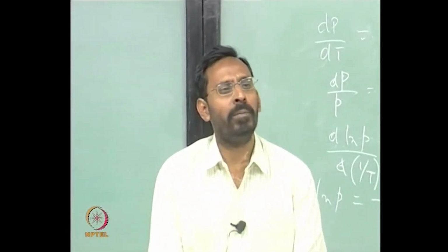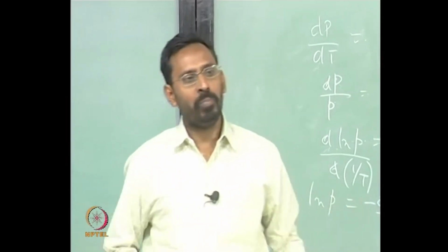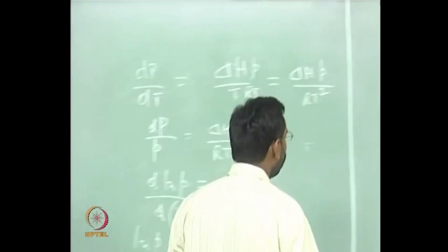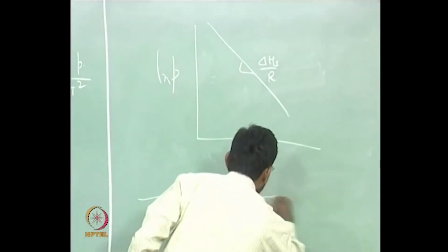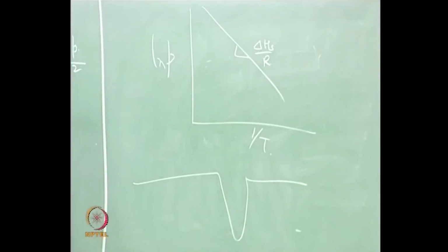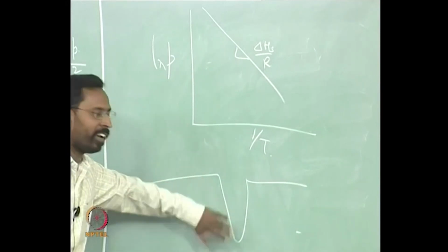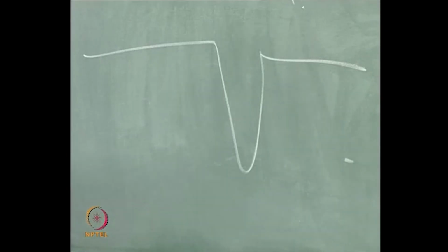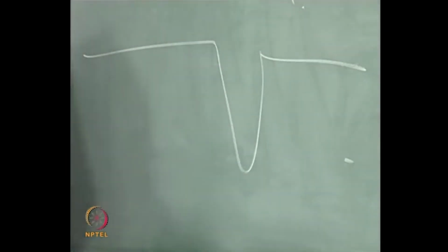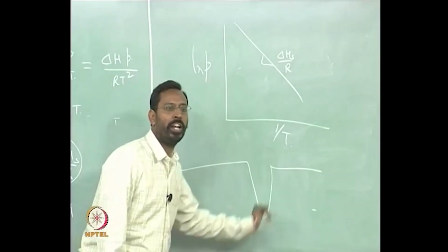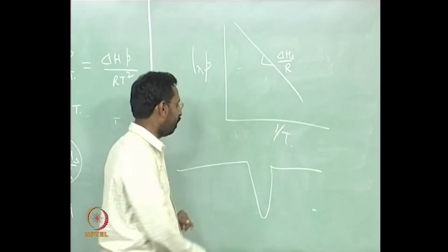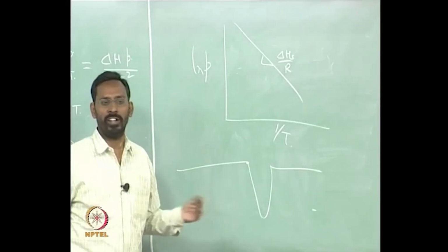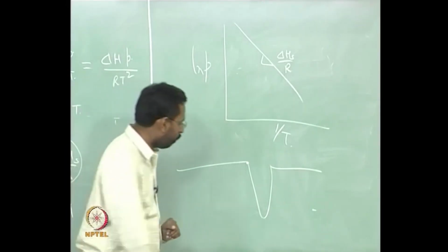So if the sublimation temperature of the material is below 1500, in principle you would see a strong peak associated with the sublimation. Of course, whether it is this side or that side depends on the polarity that we are talking about. But basically sublimation being an endothermic reaction, you get an endothermic peak at the sublimation temperature, and this basically represents the onset of the sublimation. And what does this represent?